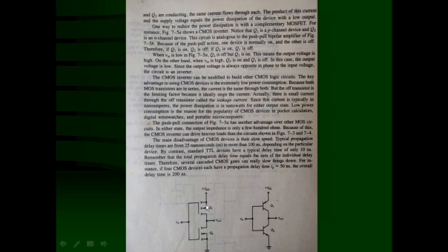So this switch is going to be closed, but this switch is going to be open. So current is very small, and this switch is going to be closed. So the VDD voltage appears as output. So V output is equal to VDD voltage. So input is going to be 0 volt, output is going to be VDD voltage. That is going to be high.